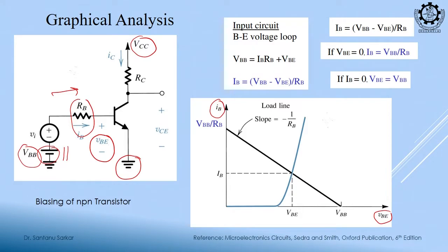But the nature of the current flowing through the resistance and the nature of the base current, are they the same? They are not the same, right. One current is exponential in nature, the other is following ohmic law. But what KCL is saying is that IR should be IB.